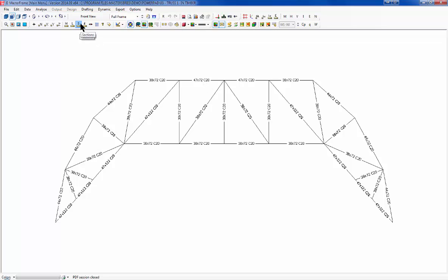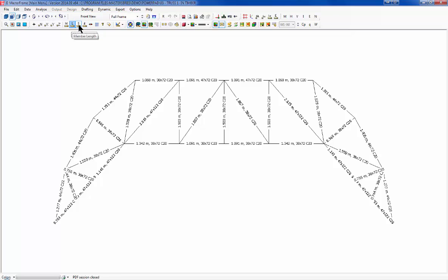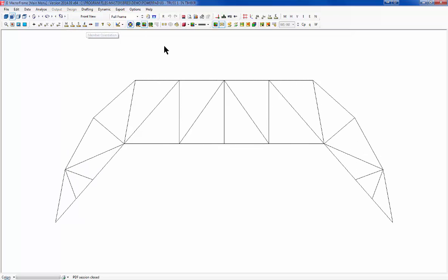So we've got all our different materials built in. Just turn those off. We can see our member connectivity. He's just analyzed this as a fully rigid frame. If he chooses at analysis time to do it as a truss analysis, it will at that point do it as a pinned frame for him rather than having to go in and put in the nodes and everything manually, or the releases. What I want to show you in here is the editor.